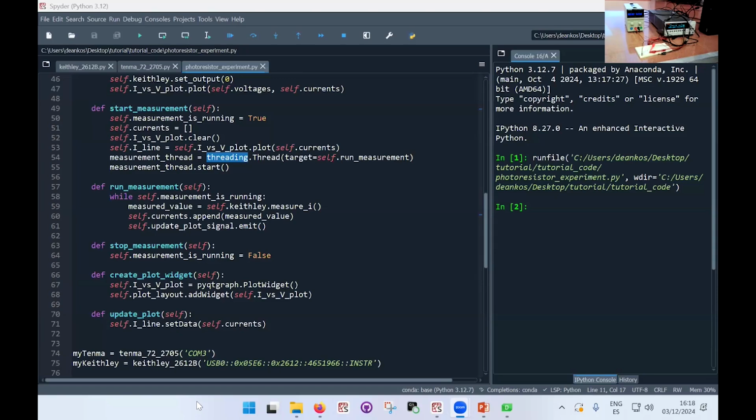I mean, the Keithley itself, most instruments will have a digital output somewhere, like a trigger output. So it depends how you want to do it. You can do everything from Python. You interact with one instrument, you interact with the other. You make them do things more or less at the same time. That's the thing, you can't control the timings from Python with incredible accuracy. So you can do it up to a point, up to an accuracy, I would say, of the order of milliseconds, which is the interaction time of the communications. So you can take one Keithley, then the other, and in the code, you just make them do different things. In my experiments, I often would do that if timing is not particularly critical. But if timing is critical, then you'll have to go beyond that.